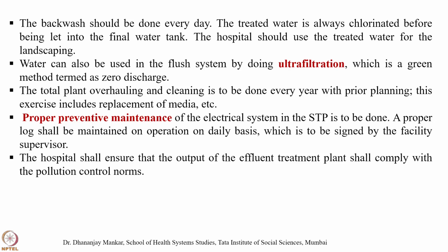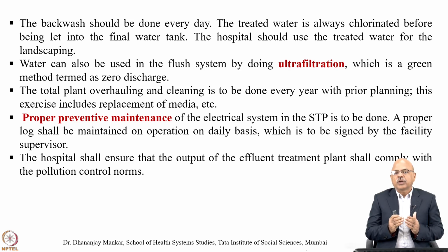The backwash should be done every day. The treated water is always chlorinated before being let into the final water tank. The hospital should use the treated water for landscaping. Water can also be used in the flush system by doing ultrafiltration, which is a green method termed zero discharge. The total plant overhauling and cleaning is to be done every year with prior planning. This exercise includes replacement of media.